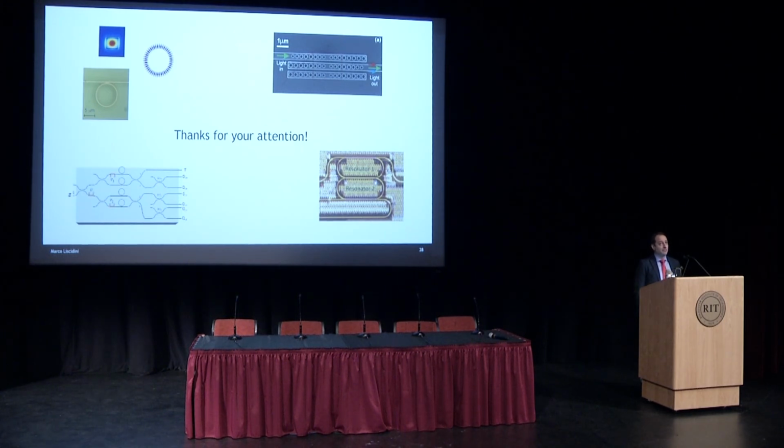I find it extremely interesting because you can reach regimes of field enhancement that are absolutely inaccessible with ring resonators, because with photonic crystal cavities you can get Q of the order of a million, but with volumes that are orders of magnitude smaller than a ring. So clearly this is exciting from the physical point of view. From the engineering point of view, though, we have to acknowledge that at the moment this cannot be the way to go if I want results in 5 years. This is not possible. But we also have to look a little bit farther than that, in my opinion.